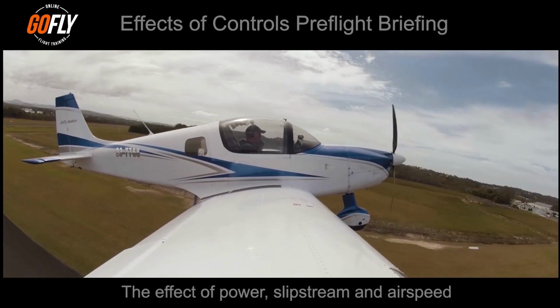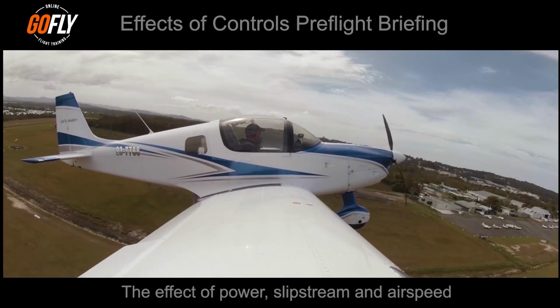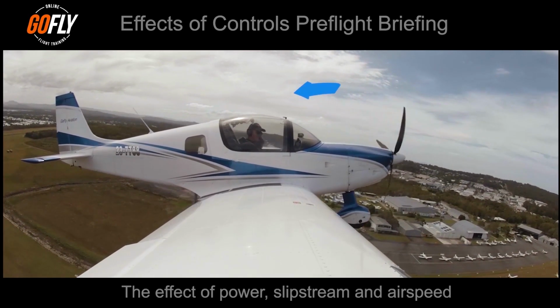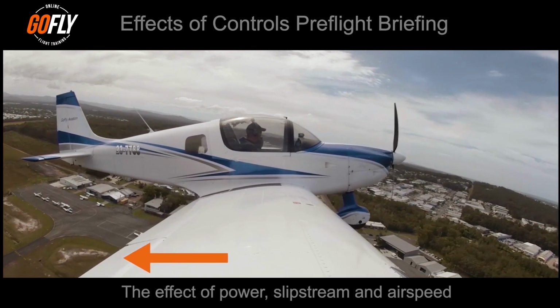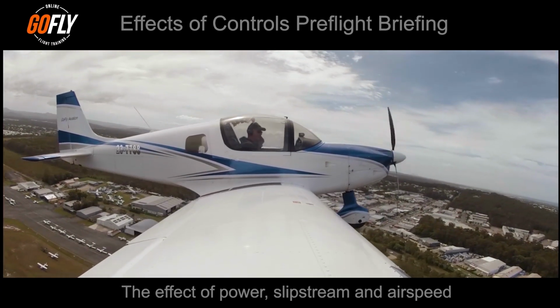During some stages of flight, for instance on takeoff, we have more airflow being produced by the slipstream of the propeller. This propeller slipstream may make the elevator and rudder that are exposed to this slipstream feel firm and responsive even if you are flying at a lower airspeed. The ailerons, being situated outside of the propeller slipstream, may still feel sloppy.